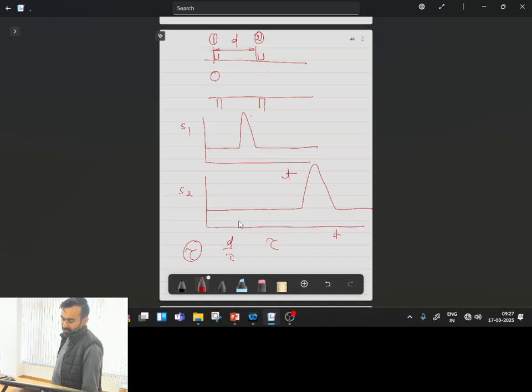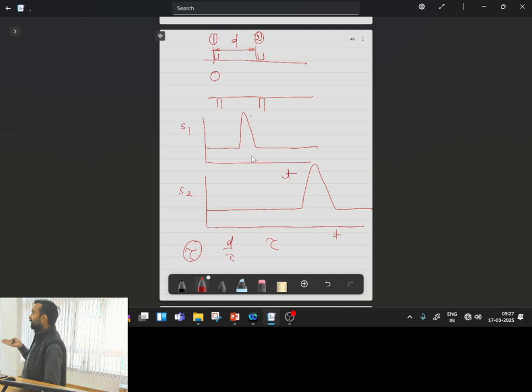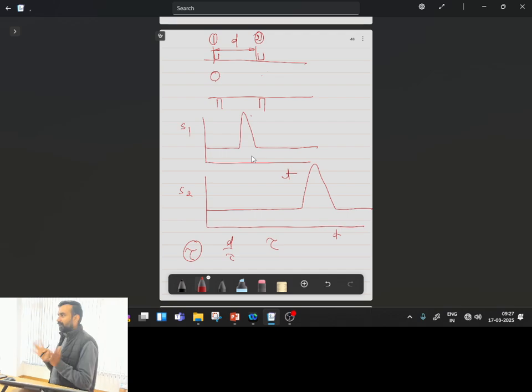The cross correlation method has one disadvantage. If one signal is positive and the other signal is negative, then the product of the multiplication can be negative, and ultimately the peak value in the final quantity will be less.